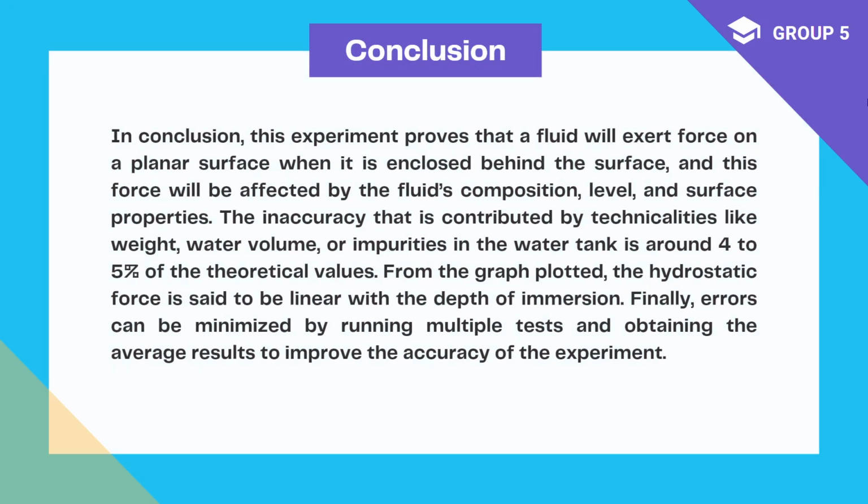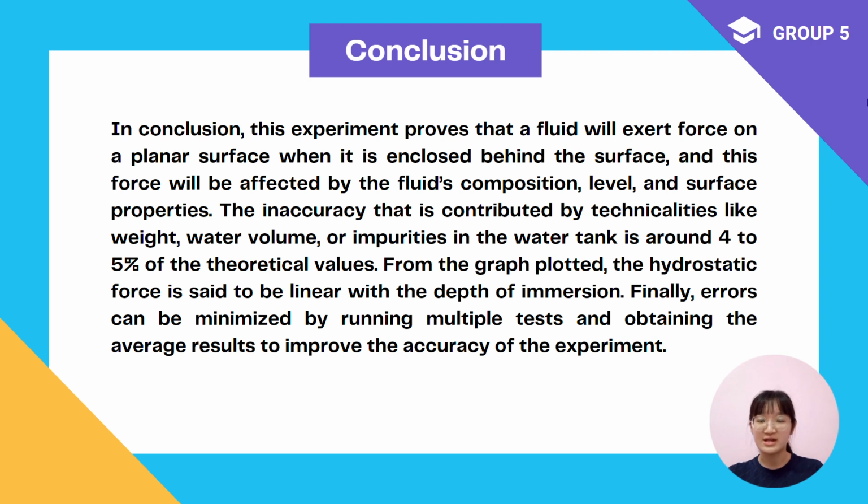experiment. In conclusion, this experiment proved that a fluid will exert force on a planar surface when it is enclosed behind the surface, and this force will be affected by the fluid's composition, level, and surface properties. The inaccuracy that is contributed by technicalities like weight, water volume, or impurities in the water tank is around 4 to 5% of the theoretical values. From the graph plotted, the hydrostatic force is said to be linear with the depth of immersion. And finally, errors can be minimized by running multiple tests and obtaining the average result to improve the accuracy of the experiment.